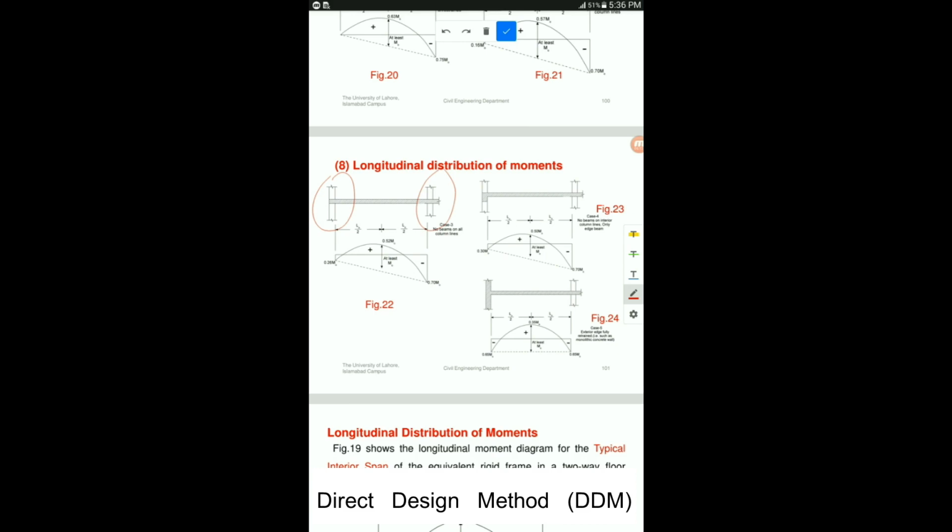So we're going to use these coefficients: 0.26 for location 1, 0.52 for location 2, and 0.70 for location 3. These are the coefficients for computing moment at the first 3 locations, and the rest of the 2 locations are the typical ones. Just note down these 3 values.